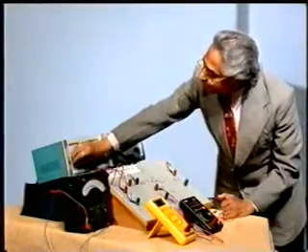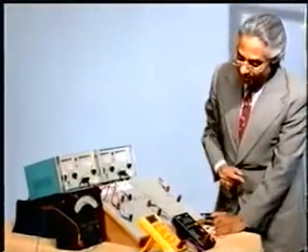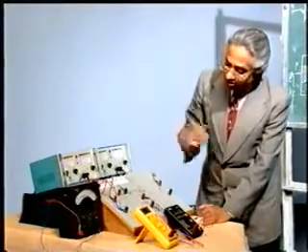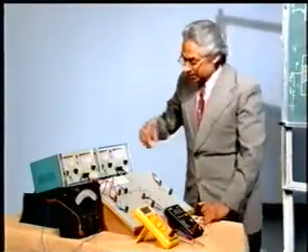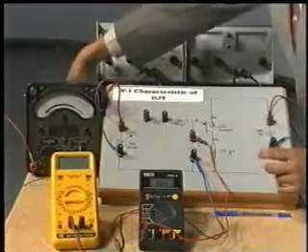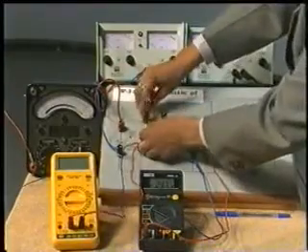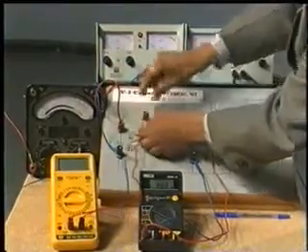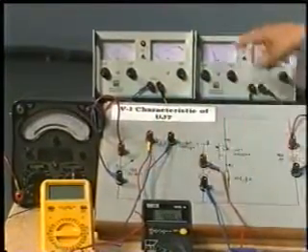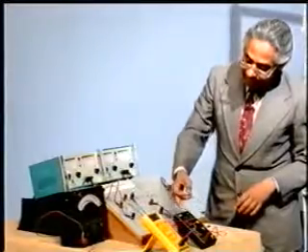Now I again put it to 0. I will replace this multimeter with the help of this digital multimeter and use it as a meter. Why I am going to do it? Because I want to note down the corresponding values of the currents also. So let me replace this multimeter and connect this multimeter over here. So the positive will come here and the negative will be connected here, and again here the voltage is fixed, and again I am going to change the voltage in steps, note down the voltage here and the current here.